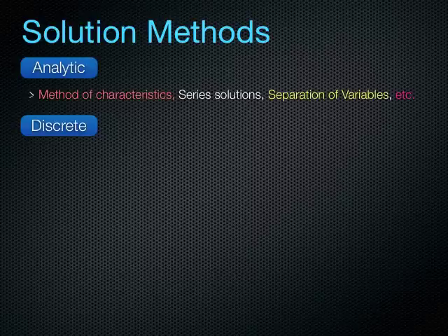These little small domains are called finite elements. And the idea of having these small domains is that even if the solution is irregular and very complicated in the whole domain, if you focus on a small region of this domain, a tiny finite element portion of it, the solution there will be more or less regular. So we can use lower order functions to approximate the solutions over this little domain, which is non-overlapping with other domains, and then hope to obtain a good approximation.